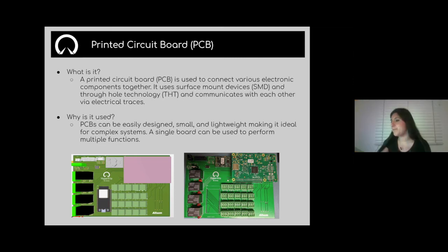You mentioned earlier, there's a lot you learn in the debugging process. And also rewiring the crowbar correctly. The crowbar is a protective circuitry we put for over voltage, but when we tested it in lab, it did not work. And in the end, it ended up frying the breadboard, and it was quite a scene. But before that, we were able to figure out the proper implementation. And so we need to also make that correction. So it'll be our second iteration. Hopefully then it'll work.